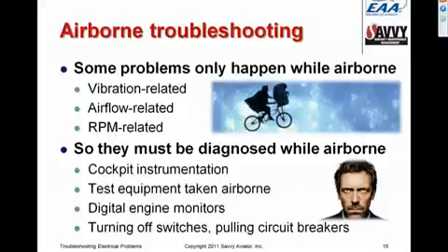To troubleshoot problems in the air, we need to use our cockpit instrumentation. As I mentioned, every airplane should have a good digital voltmeter, and actually most do nowadays, because there's all kinds of equipment that we tend to have in our airplanes that do have the capability of giving us an accurate digital readout of bus voltage.